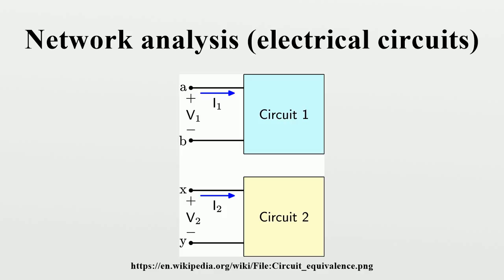It can be shown that 4 such parameters are required to fully characterize the two-port network. These could be the forward transfer function, the input impedance, the reverse transfer function and the output impedance. There are many others. One of these expresses all 4 parameters as impedances. It is usual to express the 4 parameters as a matrix. The matrix may be abbreviated to a representative element. These concepts are capable of being extended to networks of more than 2 ports.